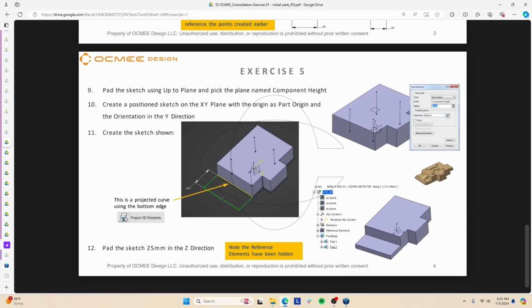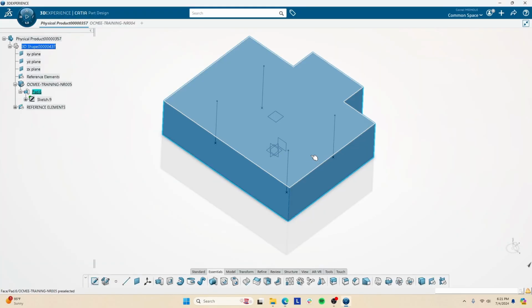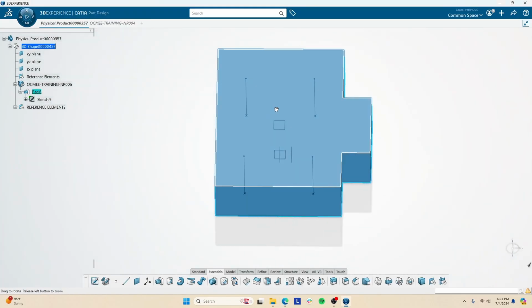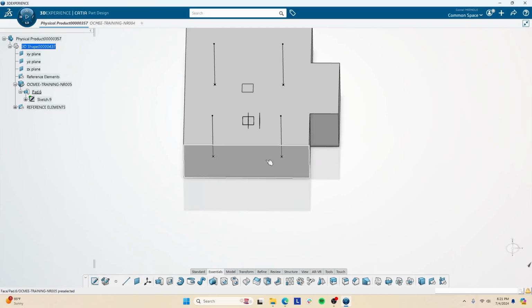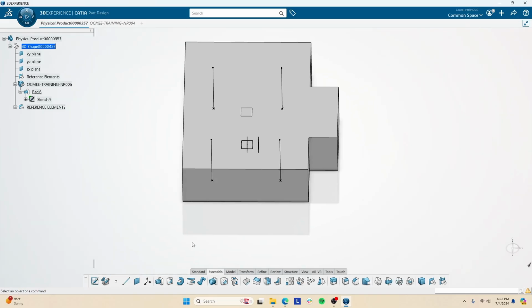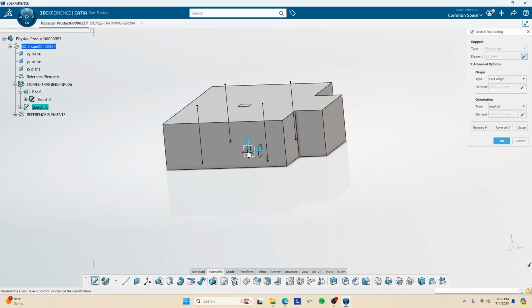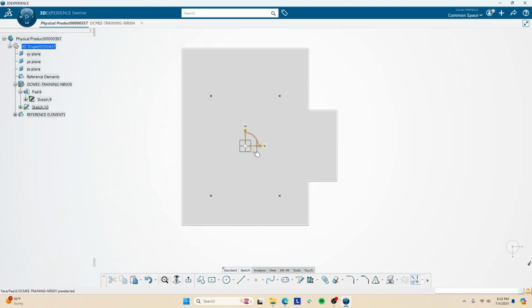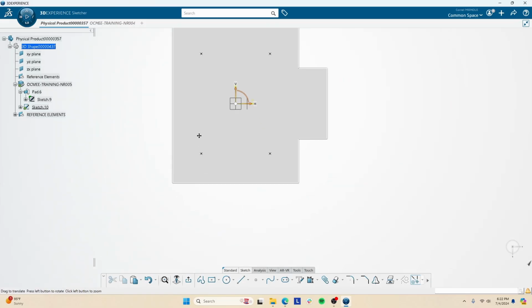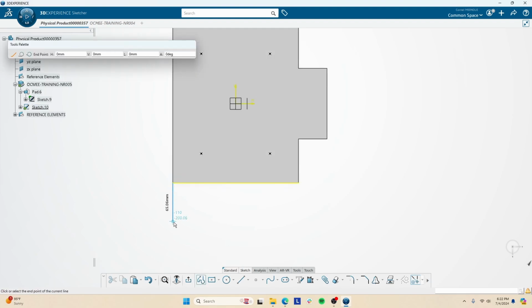And then we'll create another sketch. Roughly get it into that position, and create a sketch on this plane right here. I'm going to switch these around so H is actually horizontal. And now I could do the project 3D elements, press OK. It'll turn yellow to indicate a projected element, and I'll use the profile for the rest of the rectangle.